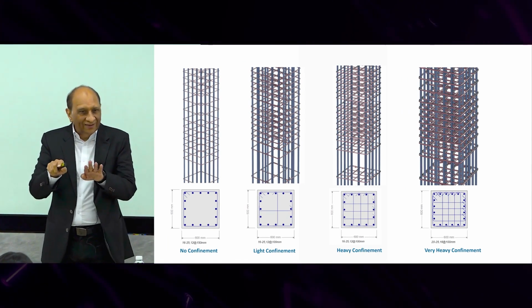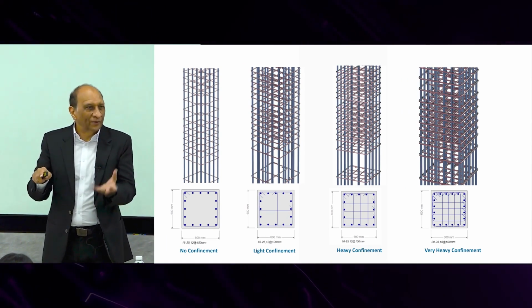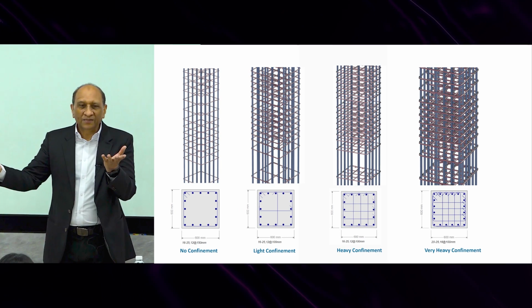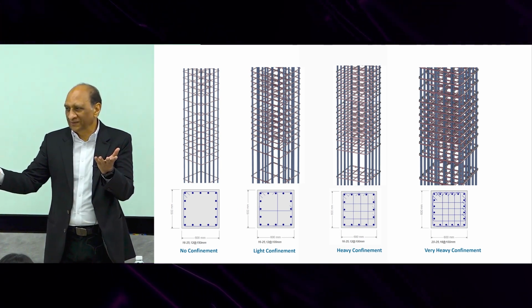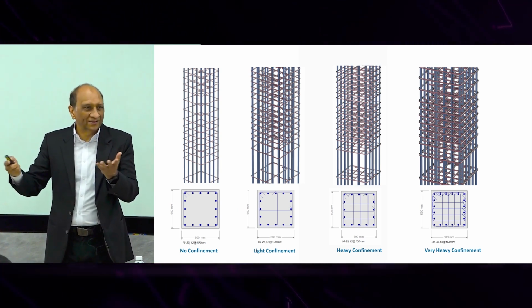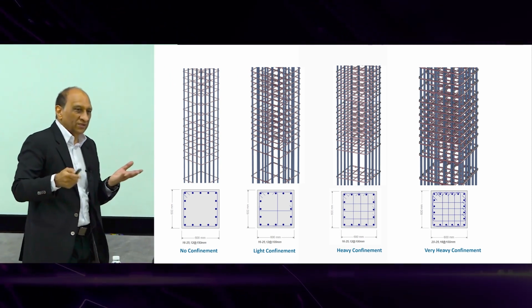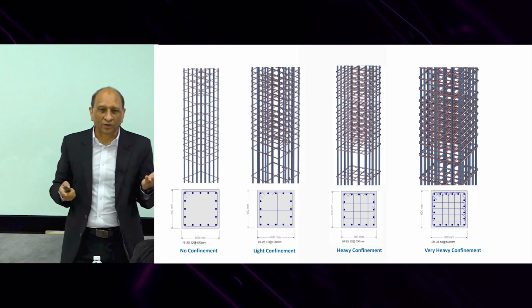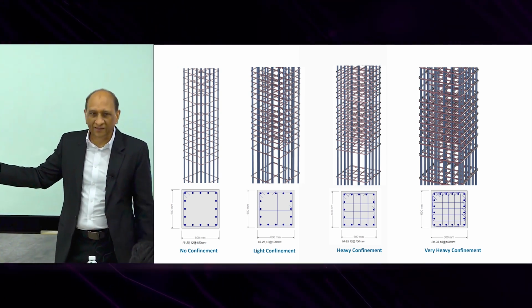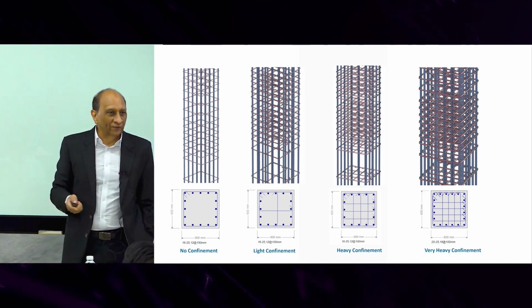But the strength design has no knowledge of this. If you calculate the moment capacity, it has no effect of the transverse reinforcement. The formula doesn't contain it; no matter how many confinements or stirrups you provide, the moment capacity is not affected. But in reality, it is affected, and that reality we can now capture.